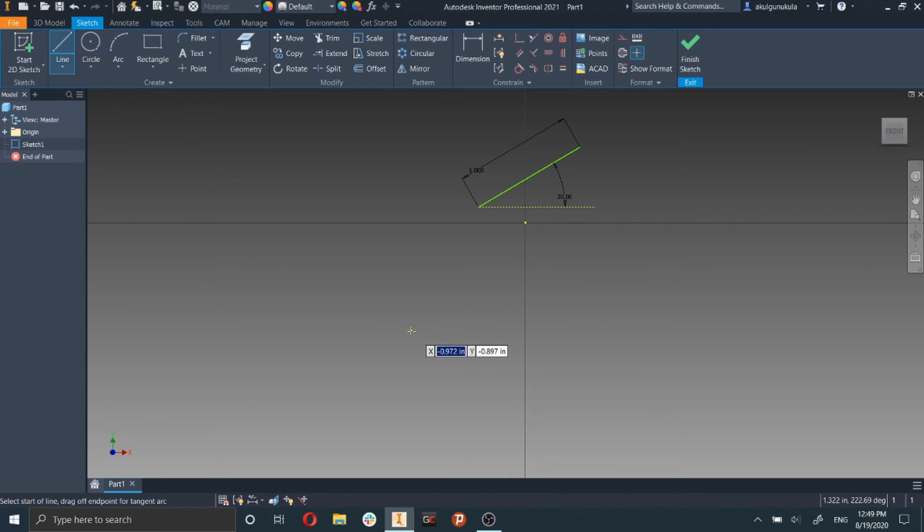So let's say we want -1, -1, correct? -1, -1, and then press the tab button again to go to the y value, -1. Now let's say you want to change the x value to 0.5. Press the tab button again to go back to the other number and then type it in, 0.5. -0.5, my bad, 0.5, and then press the enter button when you're done. So now you have the first starting point at this point that you have chosen.